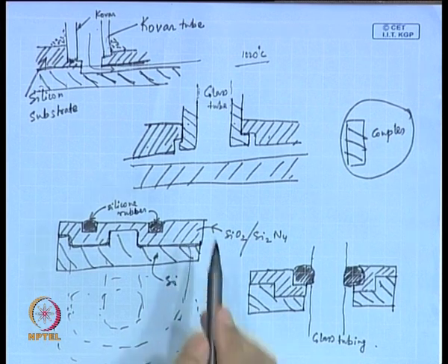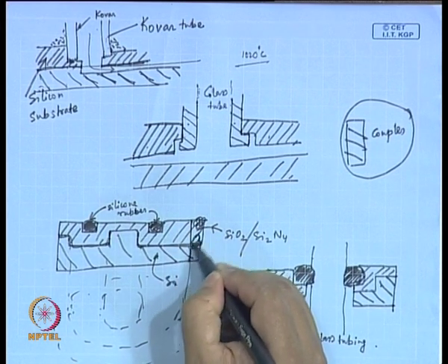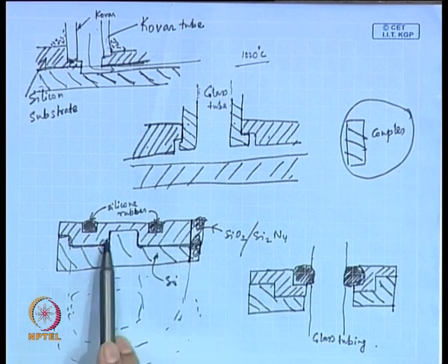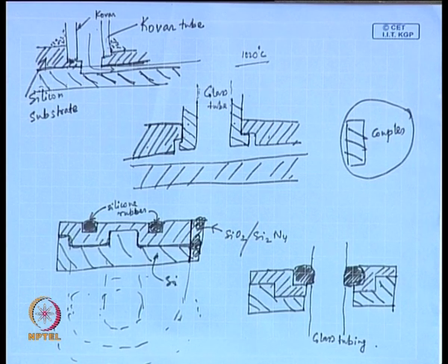Okay. So, this dip, I mean, it should have been closed here, then it would have been uniform. Okay. So, this portion refers to an annular area. You ensure this by doing an etching, you form an annular area. Then on that annular area, you deposit an oxide or nitride layer, SiO2 or Si3N4. You know how to do this deposition.